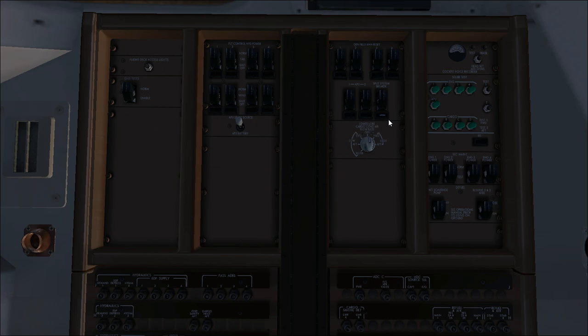All the lights are off except for the SSB, or split system breaker, light, which is open. This is automatically moved by the system itself, so it's normal that it's open and the light is on. And all the other lights are extinguished. We have to check that the APU start source is Tango Romeo, on the upper side. Yeah, it's not APU battery.